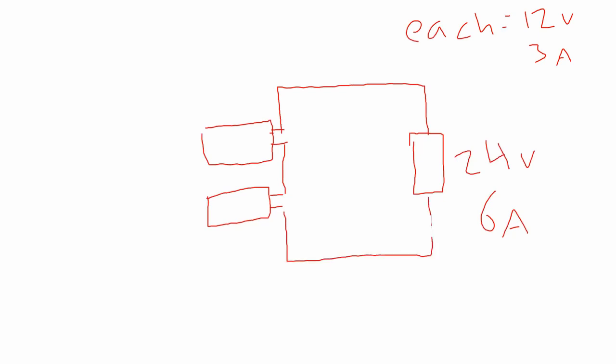Okay, so I've got this. But my voltage is good, but my current isn't enough, right? If I were to look at my current, I've got something in series, I get my voltage, but I only have 3 amps in my system. So what do I need to do to my array to get more amps? I need to add more amps by adding more panels in parallel. So we're going to add another string onto this.